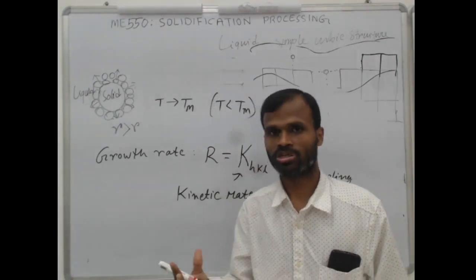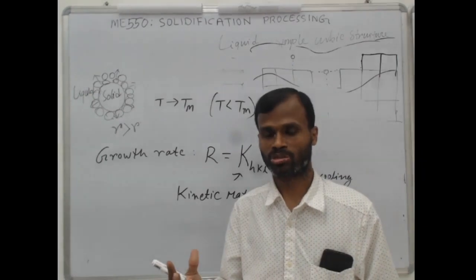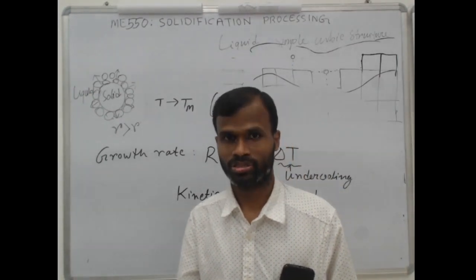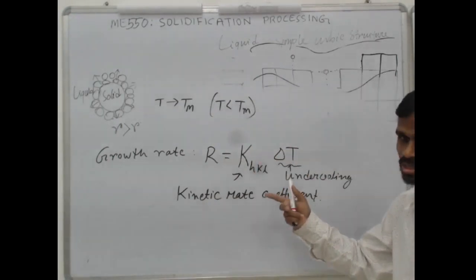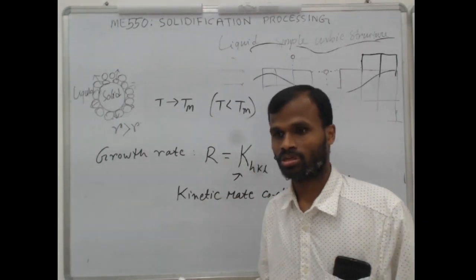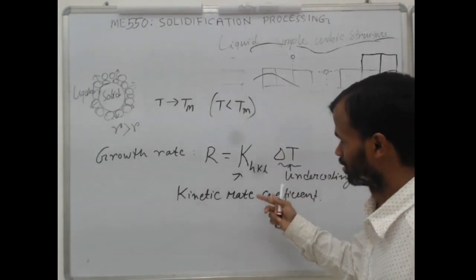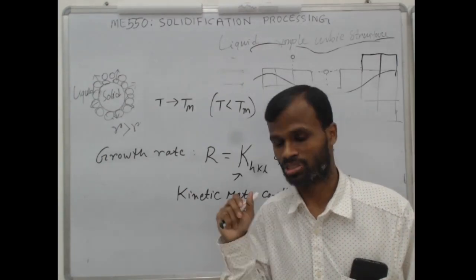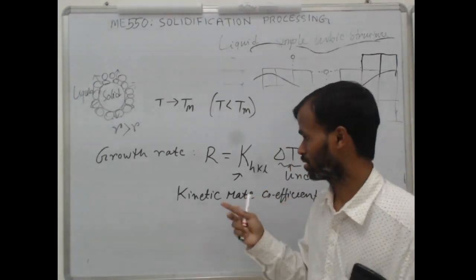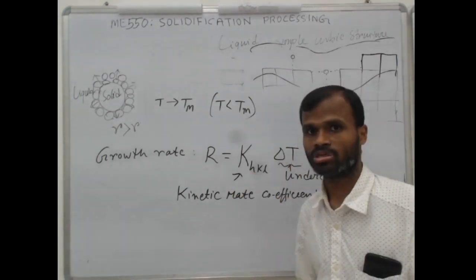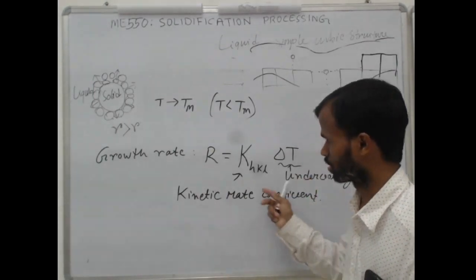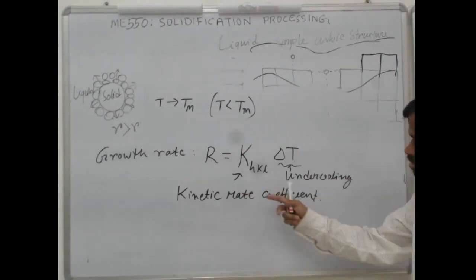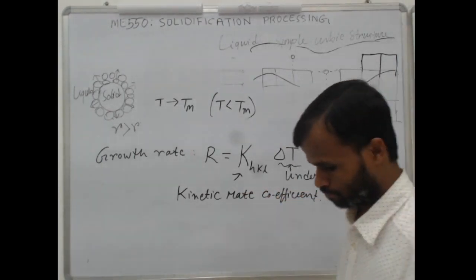Say one precipitate is being formed in a solid. If the precipitate is crystalline, say an intermetallic compound being precipitated, then what will happen? The growth rate can be different in different directions. So the morphology, the shape, will vary depending on this value of the coefficient. We will derive this relationship after this class, but just to give you some idea.